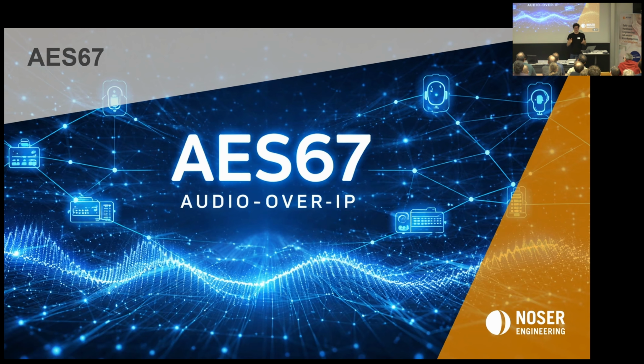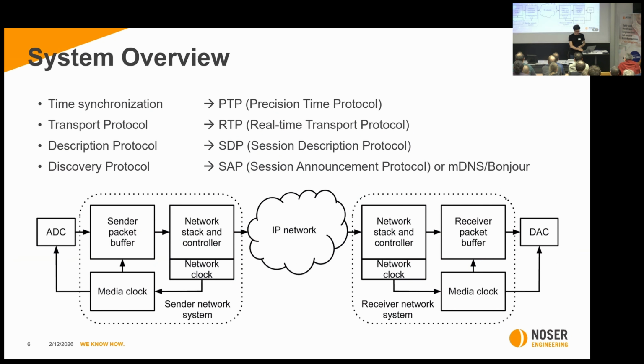AES-67 explained in 5 minutes. What technologies are actually used to implement AES-67, an open standard for audio over IP? Our system usually consists of a transmitter and one or many receivers connected over IP infrastructure using multicast. For my implementation, I focused on the receiver end because it's a bit easier to implement. The inputs and outputs could be digital audio or analog audio, depending on the application. Total latency is measured from the input of the transmitter to the output of the receiver.